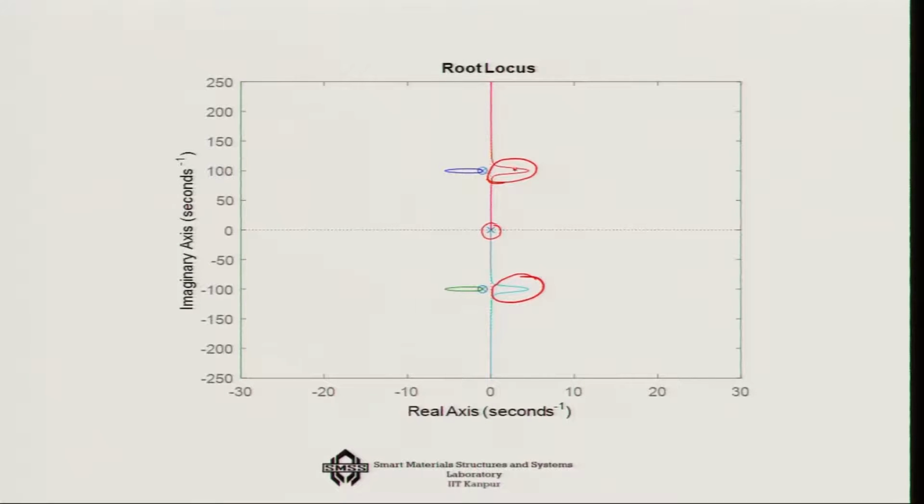Otherwise, if this does not happen, then it will follow approximately this course, provided I put a proper pole placement, which I will talk about when I discuss root locus, and you get these 2 systems as the 2 damped systems with whatever damping that you want to apply to the system. So, this is the damping ratio.